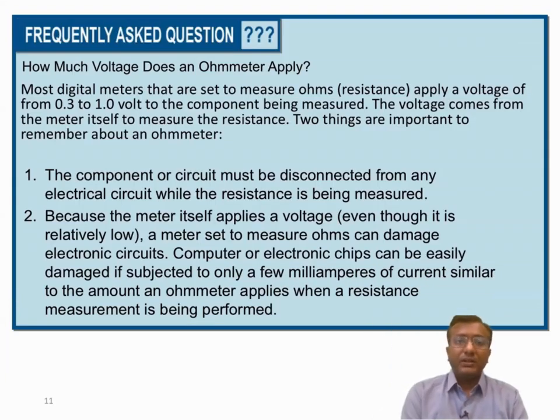And how much voltage does this ohm meter apply for measuring the resistance? The voltage is around 0.3 to 1 volt, and this voltage is very high for certain sensitive components. This can damage the sensitive electronic components which are there in our automobiles.